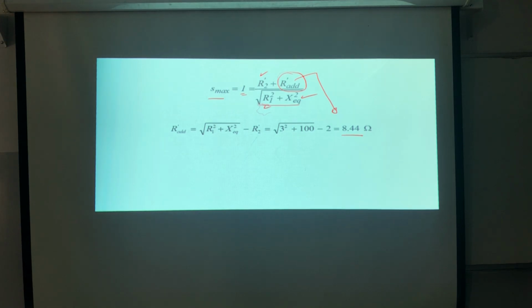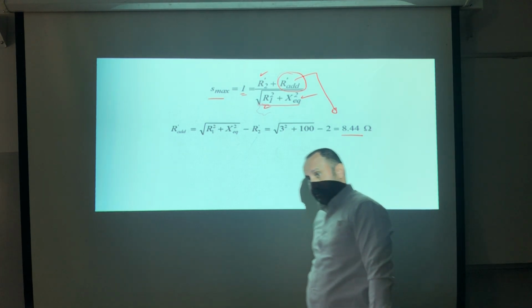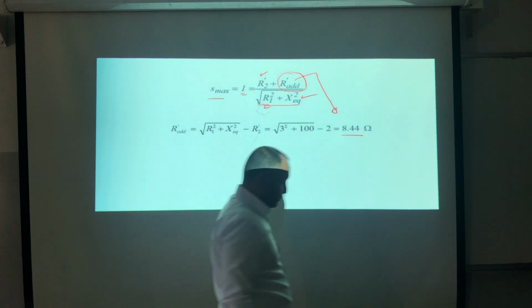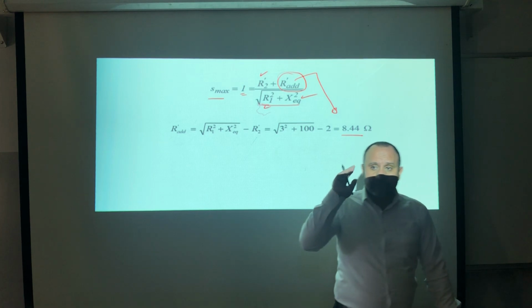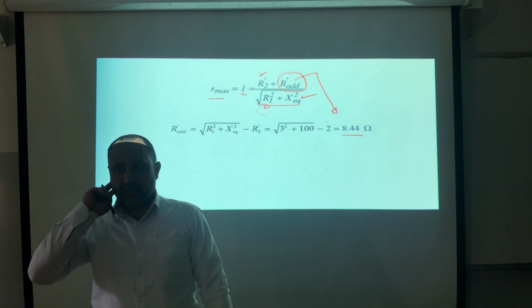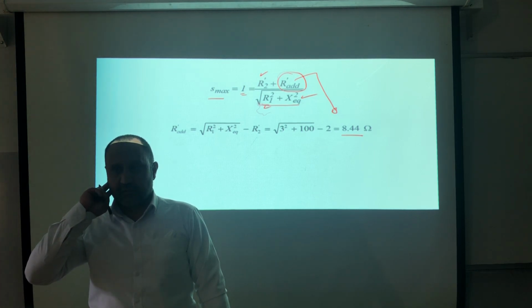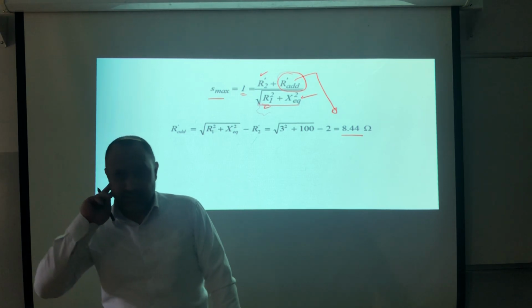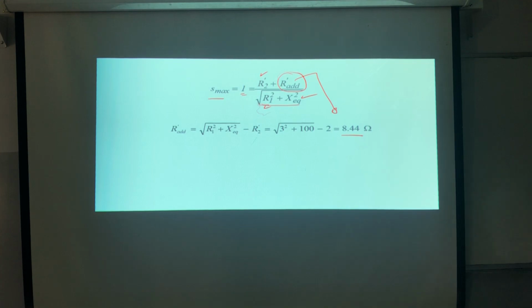If I need to calculate how much losses there are due to this modification, it is I squared multiplied by this resistance multiplied by 3, because it is a 3-phase system. I2 squared times the new R. The rotor current, the rotor current also needs to be calculated from the beginning again, right? Yes, because you are changing the impedance, of course. Do you remember the equivalent circuit now?